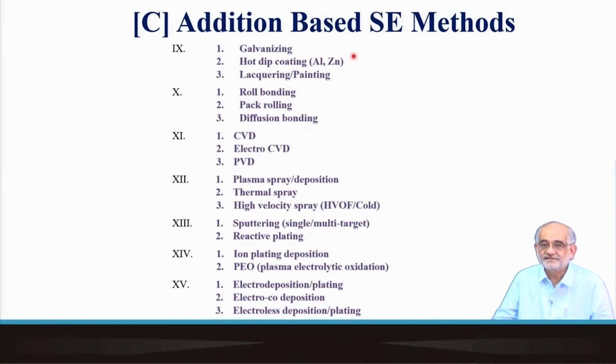The zinc is so beneficial because it allows a sacrificial coating, leaving the underlying metal to behave like a cathode, and zinc sacrifices itself to protect the underlying iron or steel or other metals that it is covering.